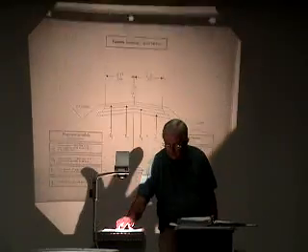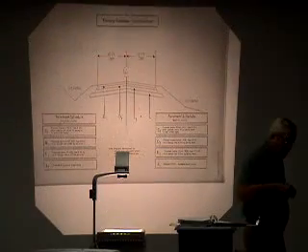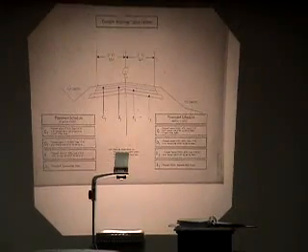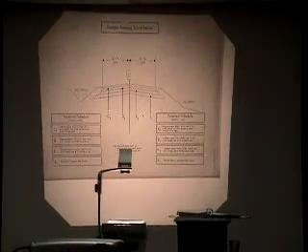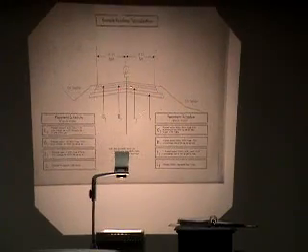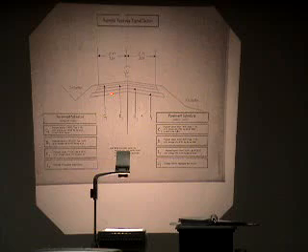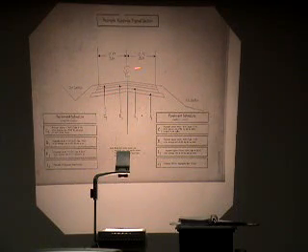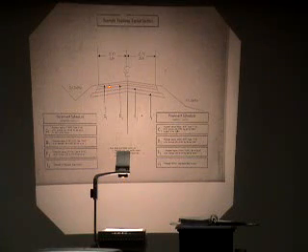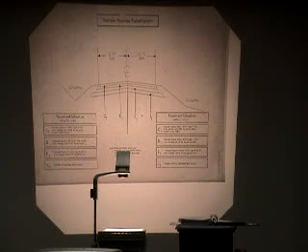And on typical sections themselves, there's one on page 3-7. Just quickly point out how you read these. As you get involved in the construction, you'll become more familiar with them. This is a very simplified typical section. The part we're interested in is the pavement section itself. And on that typical, they'll have all kinds of dimensions, width, thicknesses, and this kind of stuff. And they'll show the various layers, and they'll designate them by some means, which will refer you over to the pavement schedule. And the pavement schedule will tell you what that layer consists of.